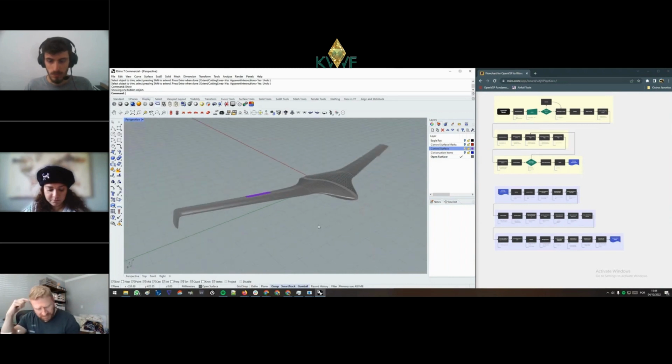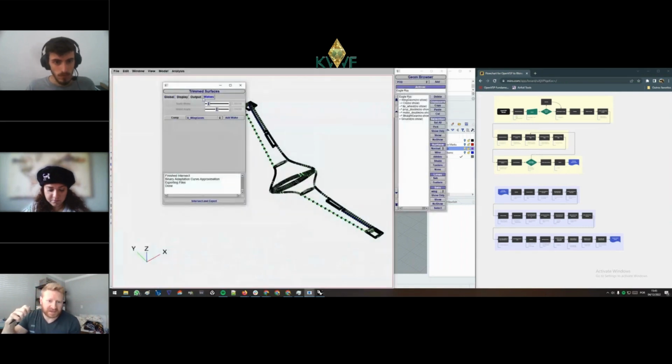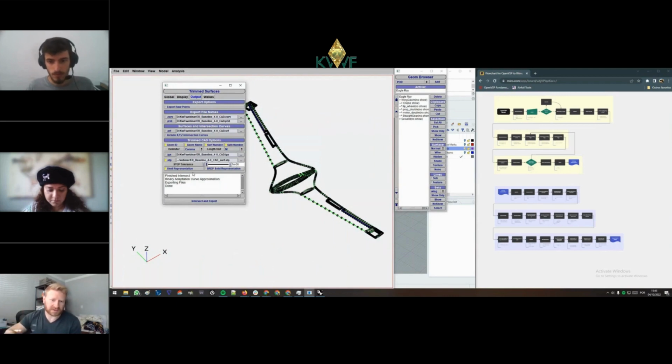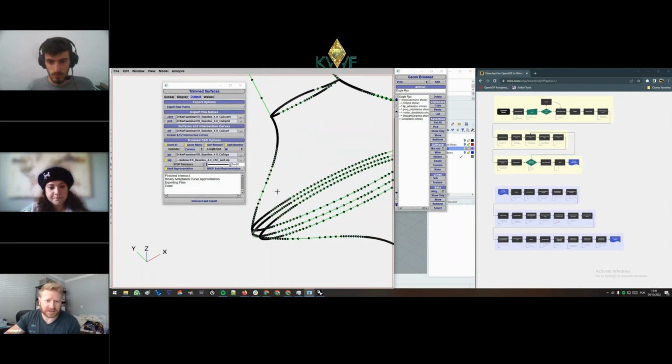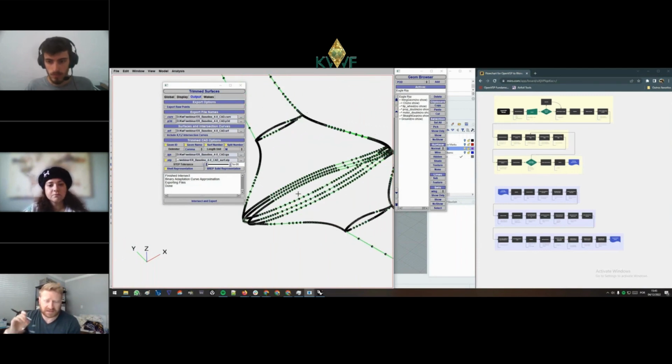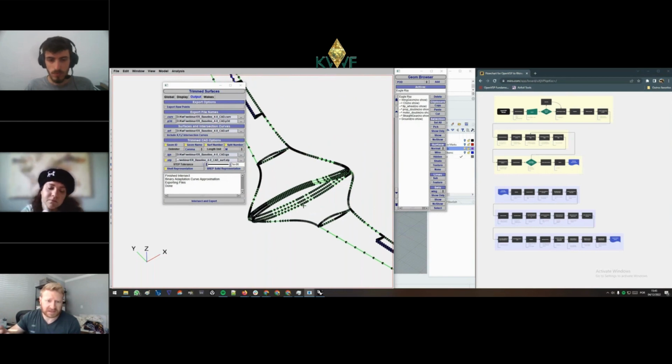So I noticed that you had curve adaptation tolerance set down to like 0.005 in OpenVSP. So you're getting quite a lot of points, especially along the chordwise direction down at the fuselage. And it seems like when Rhino brings that in, you're getting every single one of those nodes as either a feature line or a facet when you're going out as a step file.